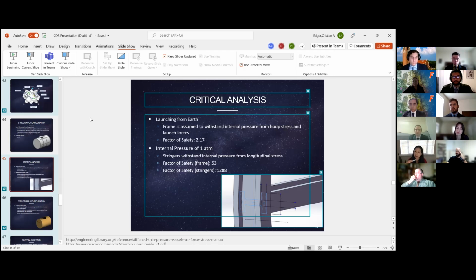They calculate the thickness in the end, and the thickness is not that much different. And this one you calculated, wow, the safety factor is so much different. So first check your calculation, and then if the safety factor is still too high, there should be some way to optimize your structure to make it lighter. It does not need to be so high. You can make it thinner, and the whole weight and the whole cost will decrease. Okay, thank you.